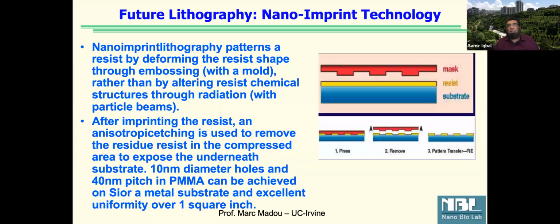So this stamping concept is another thing, what you call nano imprint lithography. Instead of using just an ink, what they are doing is they are using a coating of hard material and they press it down with high pressure and high temperature, and they transfer the design into some polymer material. All right, questions?